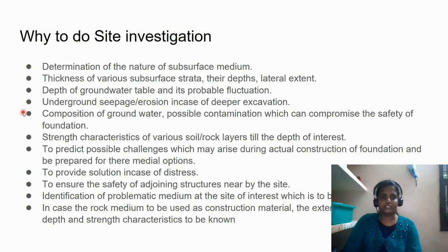If you are going to test steel, it's a manufactured material. It's going to have the same property, plus or minus, throughout the world. If you say it's Fe 415, it is Fe 415. It is going to give you the same strength everywhere. If it's M25 concrete, it means if you mix in that ratio, you are going to get M25 concrete.